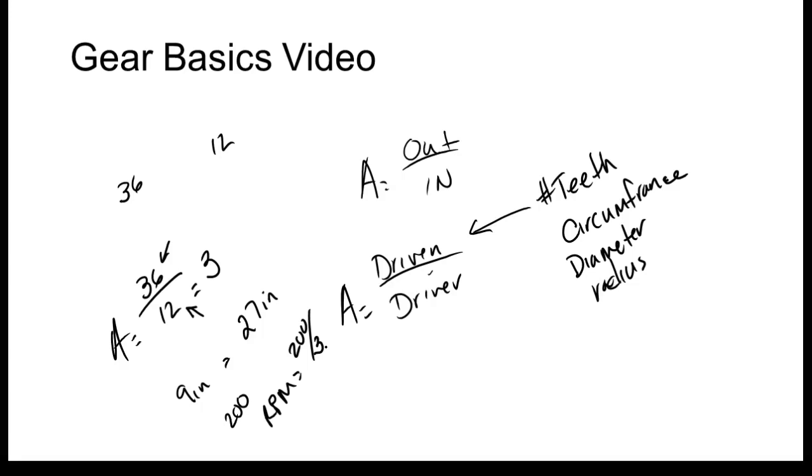So power in equals power out. We can do it at a higher torque or at a higher speed. Your car's sitting perfectly still and you're trying to get your engine to move that big old car. What do you want, a torque multiplier or a speed multiplier? Torque multiplier. Once something's in motion, it takes less torque to move it, so we want a higher speed, right? That's what your transmission does, switching gear ratios.